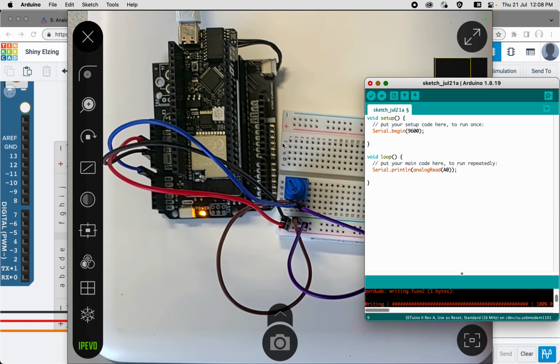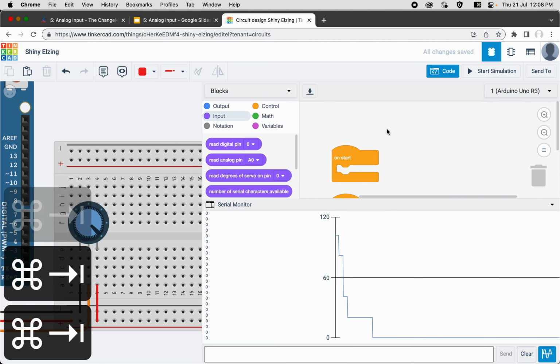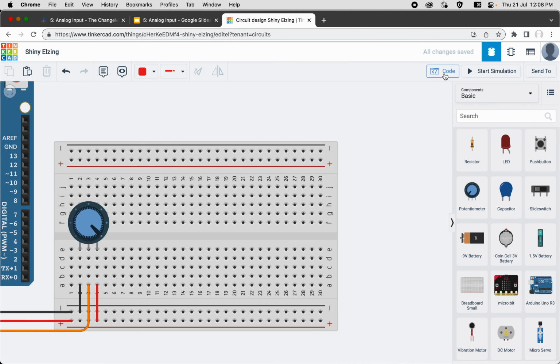Next thing that I want to do, okay, we're gonna unplug this. Now that we can do this, we know that 1 second is equal to 1000 milliseconds. We know that analog reading is 1023, okay, maximum. So we are going to use this to modify what we did previously on the blinking LED. We are going to adjust the delay for the blinking LED using the potentiometer.